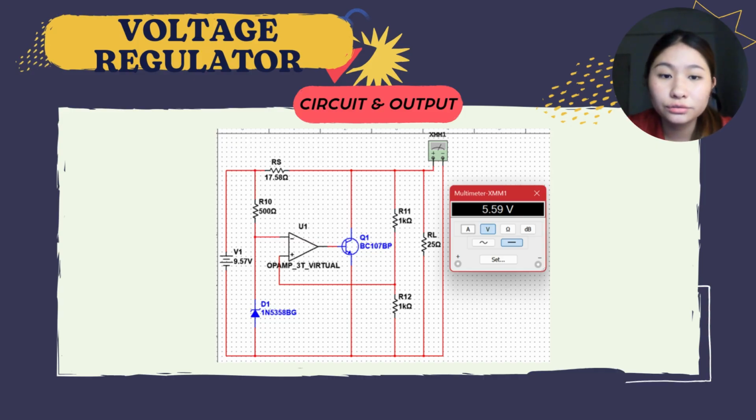The circuit shown is a voltage regulator using an operational amplifier in a shunt regulator configuration. The components used in this circuit are operational amplifier, Zener diode, current limiting resistor, 1 kilo ohm resistor, and load resistor, which is 25 ohm.